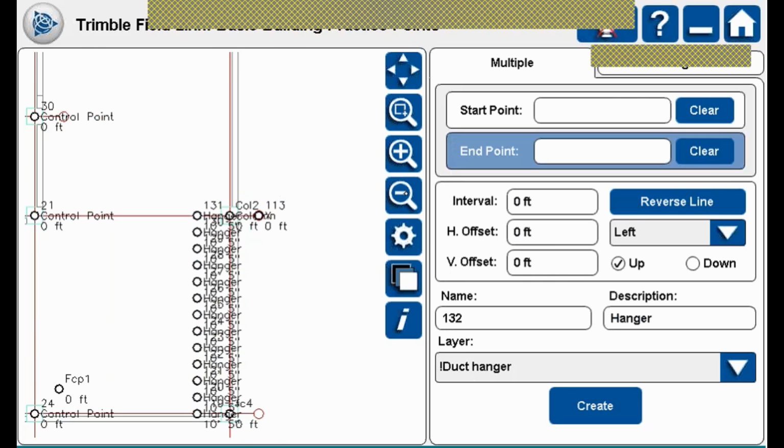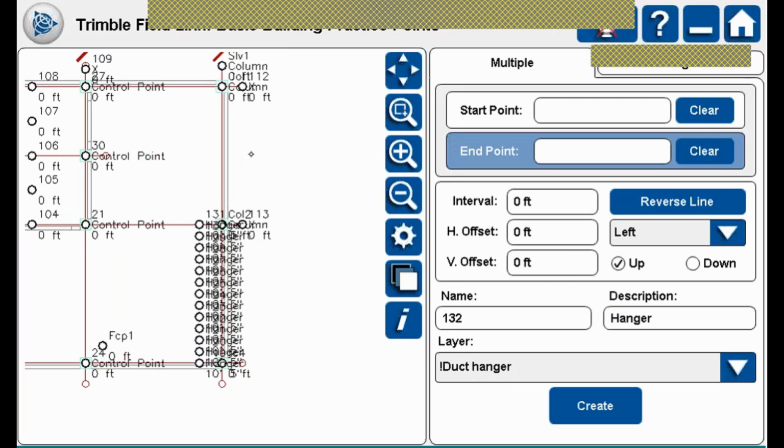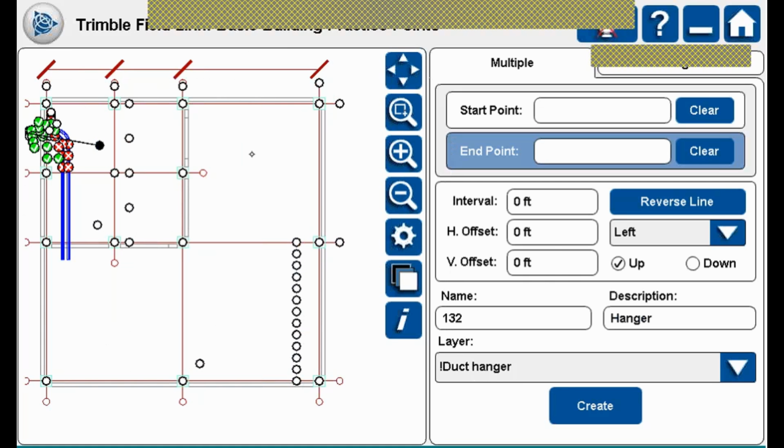So if something gets left out on the CAD side of things, and you know how far off of one column line or another that particular run of pipe or duct happens to be, you can simply create your own points and, in a pinch, keep working. Keep in mind, though, you do need 2 points to start with in order for it to figure out that reference line.